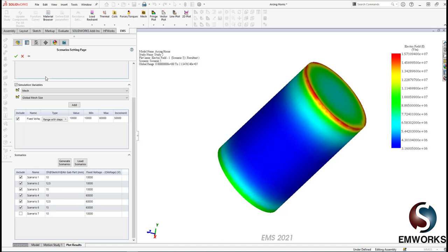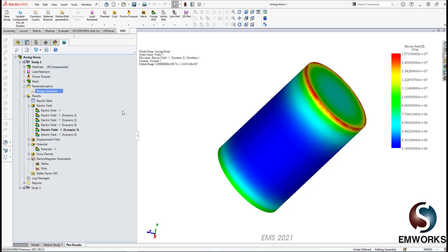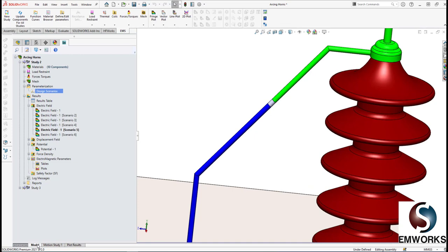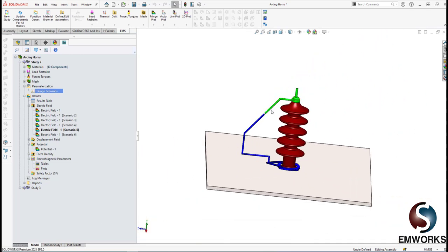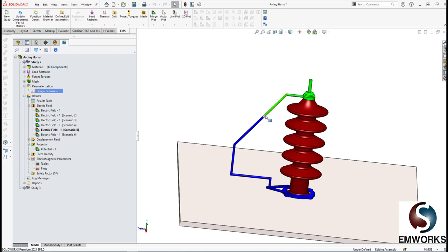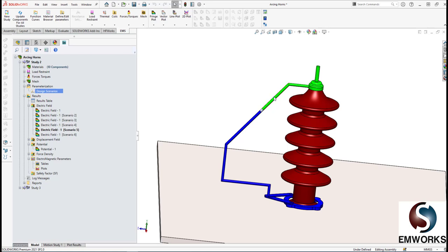This will cause the ionization of the air gap, which, in turn will cause corona, leading to an arc between the high voltage line and the ground. The arc will act like a conductor connecting the high voltage to the ground. Consequently, the flashover will go from the high voltage line to the ground via the arc. The bushing insulator is thus saved.